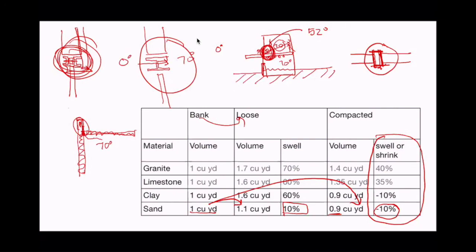But those are typically edge cases. They're important enough that if you work in a mixed or cold climate, this edge case wouldn't be so crazy. It very well may show up at some point during your career that you have this problem. So it's not rare, but the better thing to focus on is just not having the thermal bridging to begin with, and then you don't have to worry about the heat loss or the condensation.